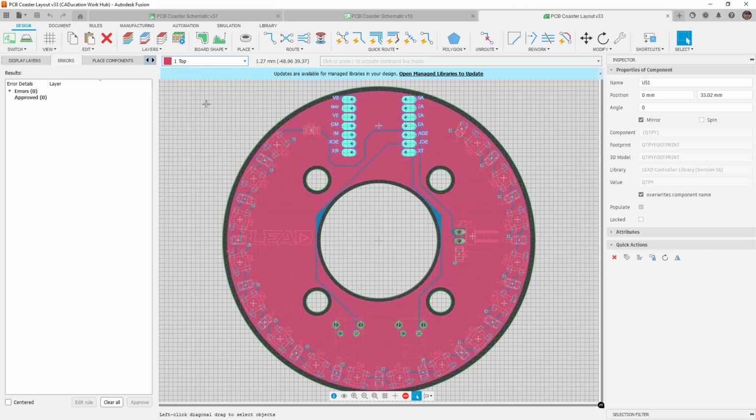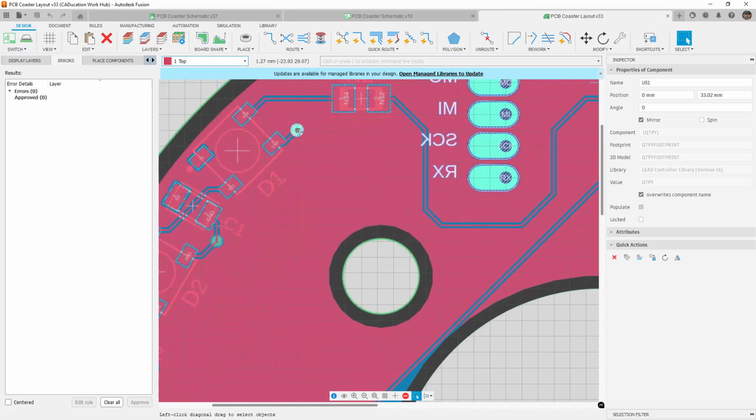And the top is going to be a power plane. Generally, what we do when we're designing these things is we try to simplify the number of connections needed. Now, having the power and ground plane on the top and bottom didn't necessarily make this very easy because all of my components, or the majority of them, are surface mount, which means that I would need to run vias or small holes through the board to connect the top to the bottom. So you can see here everywhere there's a ground connection, there's a small green dot, which is a via.